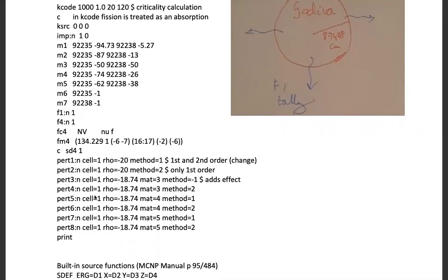Now notice that I have not specified any energy bins. I have not specified any angular bins because I just want to keep it simple for you at the moment. If I wanted to, I could have put E4 and C4 over here for this tally. I could say I want the thermal, so I could say 2.5E-8, 1, 4, 10, 20, because energy goes in MeV bins. I could say C4, it begins from -1 to 0 to 1. So I could get the F1 going backwards and the F1 going forwards.